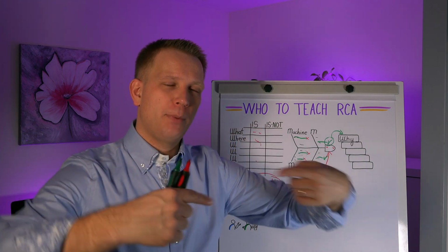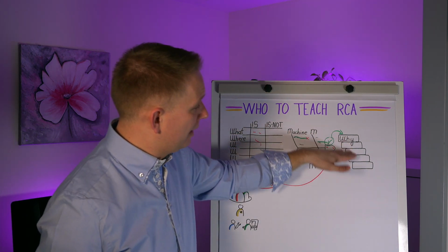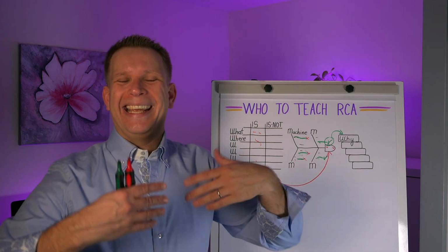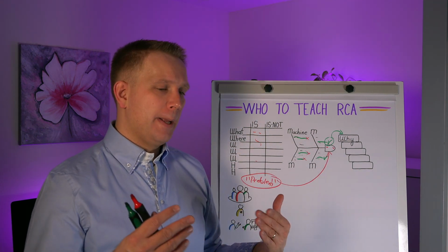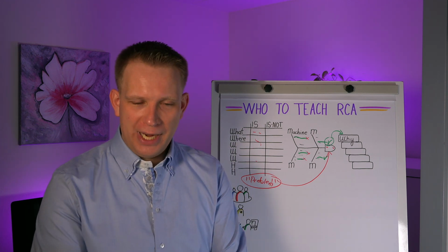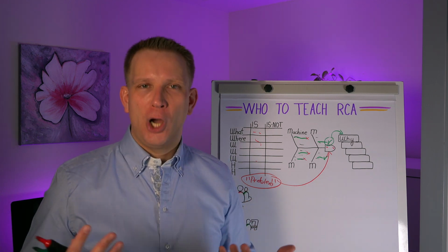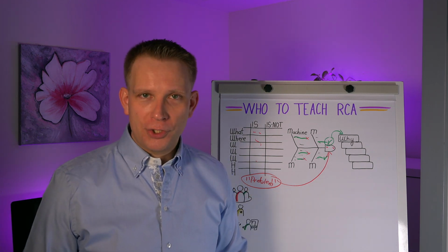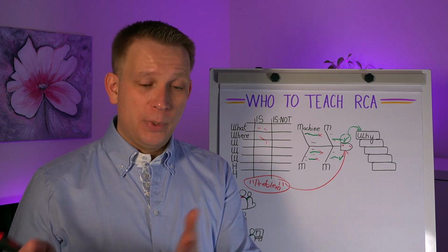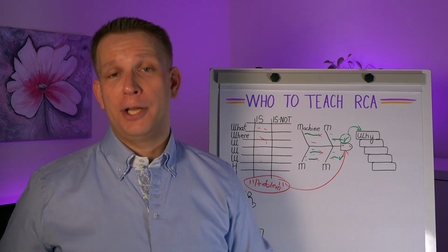But the 5 why, so this is the 2 to 3, 2 why type of level. The 5 why level goes deeper, and it is on, so how do we get that axle out of alignment? Don't we have a check for it? And then at some point you get to organizational types of root causes. Things like we don't have an inspection plan on axles and on the alignment of our machine.